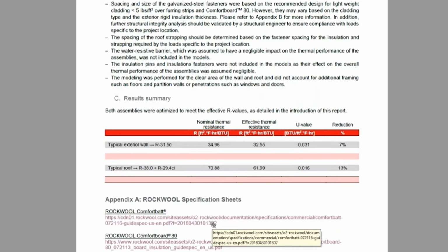For example, in this house, one of the main problems was that they just added insulation and didn't consider other factors. It used to perform well, and probably didn't have rot or any mold in the beginning. But once they introduced the insulation, they reduced the heat loss, and the heat loss used to make the siding always dry because of the heat transmitted from the inside of the house to the exterior. Once you introduce insulation, that significantly reduces the heat loss through the walls, and that will cause moisture to build up, which will also lead to mold growth.